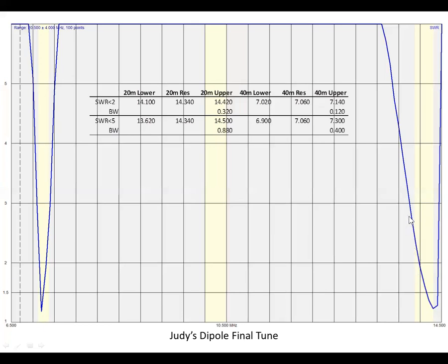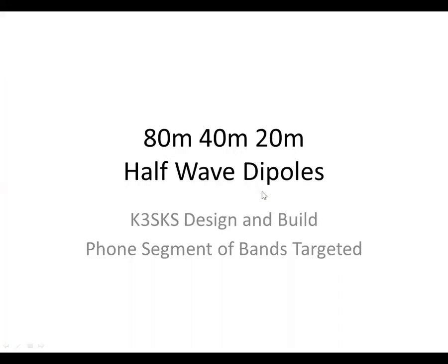So this wasn't as sensitive to the change of resonant frequency as the other one, because the bandwidth was wider. So that's kind of a real world practical application of a compromised antenna, although there are pluses and minuses for it.